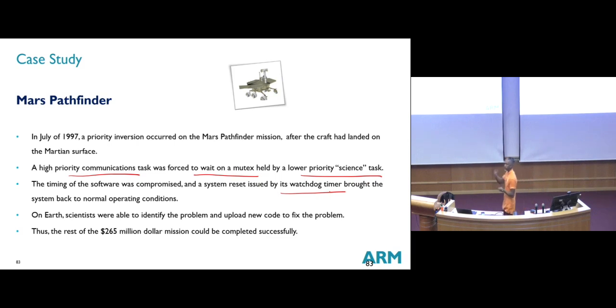Why did it reboot by itself? Because the watchdog timer kicked in. It reached a stage where it failed and cannot recover, so the timer kicks in to reboot and bring it back to a safe state. So this is a case study.